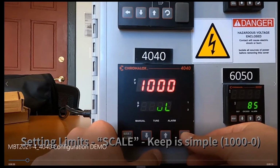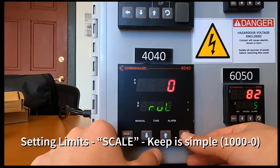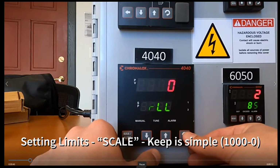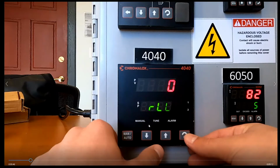So what we're doing here is kind of two things. For a linear analog input, it's really important to have this be a nice easy number like 1,000, because it's going to translate your analog signal to engineering units. So if you keep it at 1,000 and 0, if your analog input is sending like 50%, then your engineering units would convert that to like 500 Fahrenheit, if that makes sense? So it's going to take that milliamp signal and turn it into an engineering units, degrees Fahrenheit type of signal.